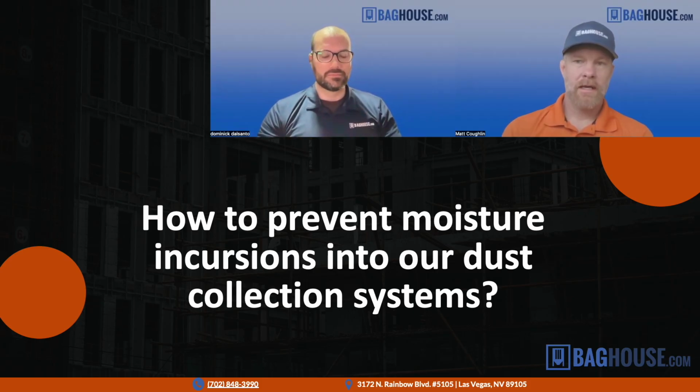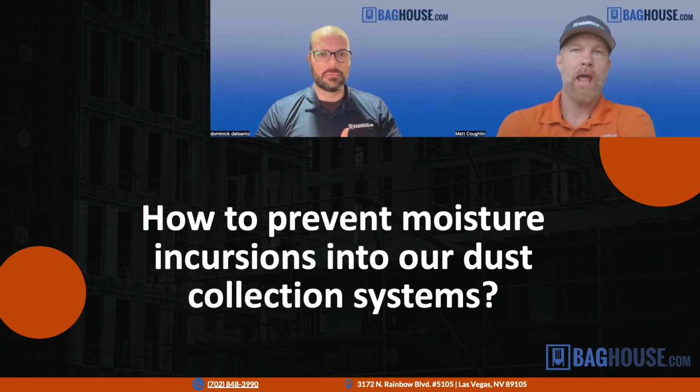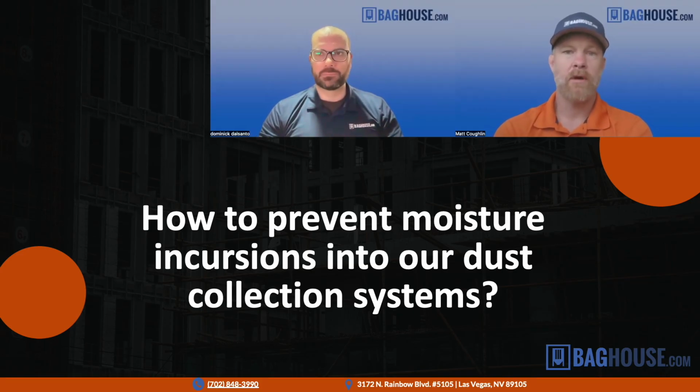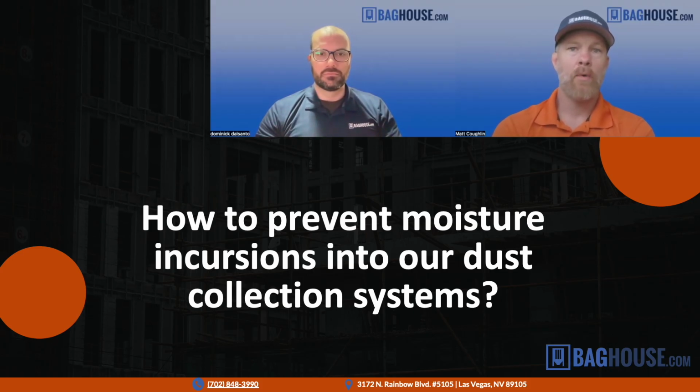Right. And can I piggyback on that? Sorry, Andy. Just for more general, ambient temperature applications, as a general rule, you don't want moisture getting in your baghouse. Basic maintenance becomes important. If you have a baghouse that's outside, you don't want moisture getting sucked in the access doors and things like that. So basic maintenance is important. Checking your door seal should be a part of your quarterly, if not monthly, preventive maintenance procedures so that you have an airtight enclosure in the baghouse.